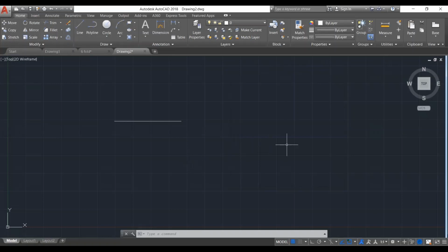The second thing, and it's important to make it before drawing, is to use your layers. Layers are important because they can prevent me from deleting the lines I don't need, like the grid, the polygonal grid, the single line, the double line and so on. I need many layers when I'm drawing patterns. So I can use more than one layer, and you will see how this will facilitate the drawing of the pattern.